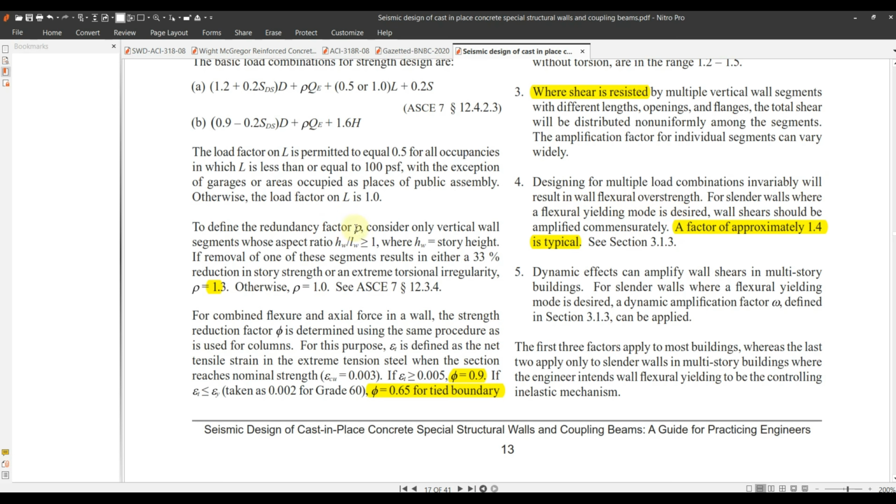It means that if you design a wall for one load combination, say under that load combination you have 1000 kN-m bending moment, and you have provided 1000 capacity to your wall, then there is no overstrength. But if you have 5 or 6 load combinations, one has 1000, another 1200, 1500, 1800 bending moment, then you are having some overstrength there, because you don't know what bending moment your structural wall will face. However, under earthquake, your wall will face that earthquake inevitably. There is no avoiding that.